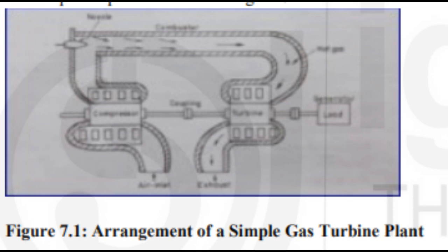7.2.1 Gas turbine. Construction. The basic construction of a gas turbine employs vanes or blades mounted on a shaft and enclosed in a casing. The flow of fluid through the turbine in most designs is axial and tangential to the rotor at a nearly constant or increasing radius. There are two types of blades used in all turbines, those that are fixed on the rotor and move with the shaft, and those that are fixed to the casing and help to guide and accelerate or decelerate the flow of fluid, being called fixed blades or vanes.